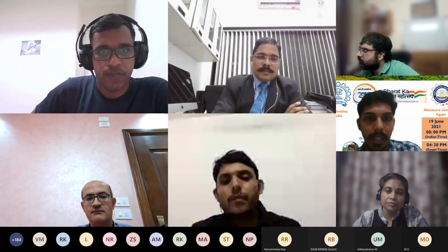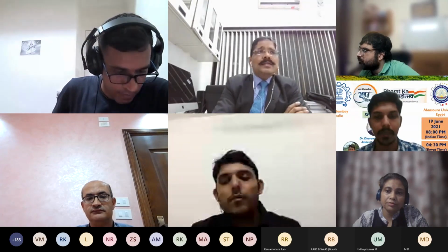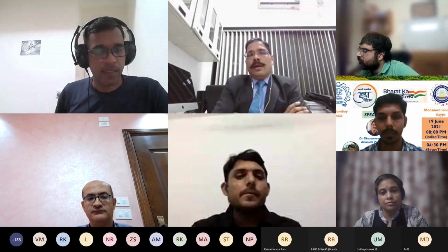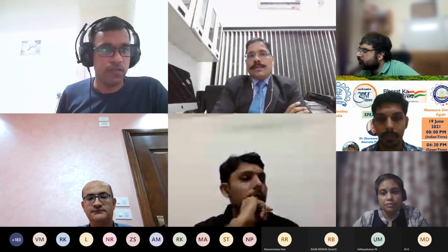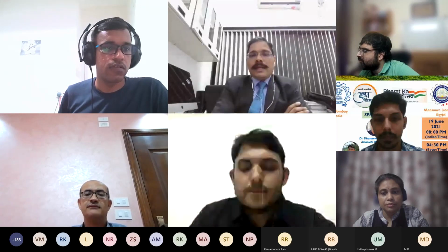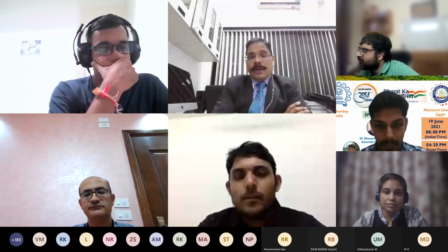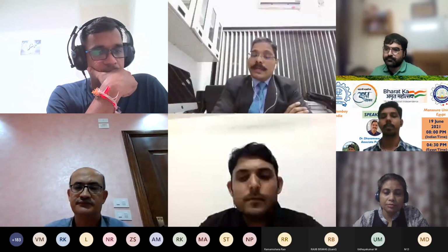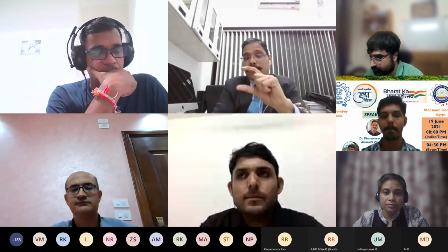I request Professor Singh to add. Yes, I think this is what it is, and also you need to be very, very careful about the thickness to nominal maximum aggregate size ratio. It is very, very critical, because it depends on what kind of aggregate size you are using and what thickness of the layer you are providing, only that particular mat.